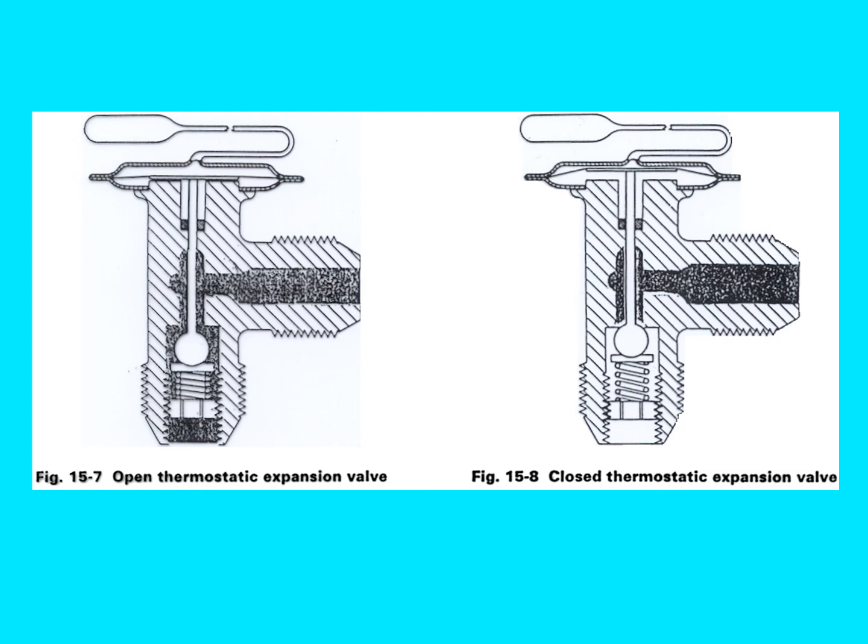This is just showing the expansion valve being moved due to the temperature inside the capillary tube sensing bulb. Okay, so open, the pressure is high enough. Now we're going to move this down off the seat. They refer to this as a pin on some of these. And it's going to move the ball down off the seat so that the liquid refrigerant can flow through.